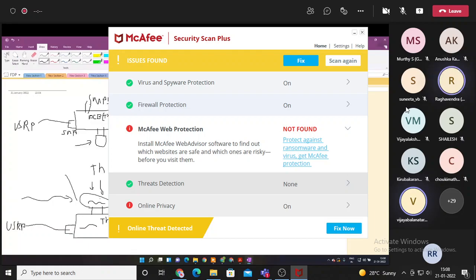The grade of the photodiode should be good, and the angle it covers should be good. The one that we have bought covers about 15 degrees, if I'm not wrong. But the advantage is that this LED gives out light in a lot of directions, so it will come within the range of the photodiode, and there's no need to worry about the photodiode not receiving the signal.